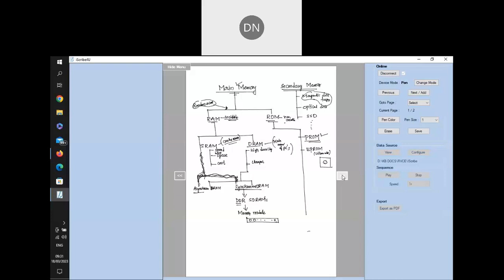That means physically you have to remove the chip from the board where the EEPROM is, take that chip to the ultraviolet UV eraser, place it into the UV eraser and keep it there for 10 minutes, then the contents will be lost. Then you bring it back and connect to your modules, or there's an EEPROM programmer, through which you program it. Earlier days we were paying 30 rupees, 40 rupees every time we changed anything in the code, so we had to be very careful. If there was a mistake in the program, you had to remember 30 rupees is gone. Again, we had to go to the place where the eraser is, erase it, get it programmed, and come back.